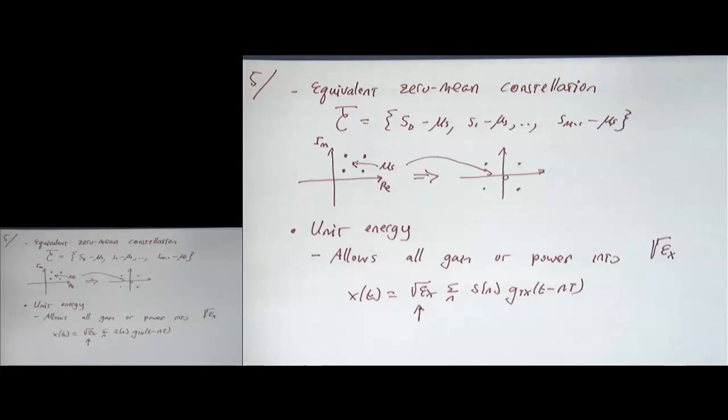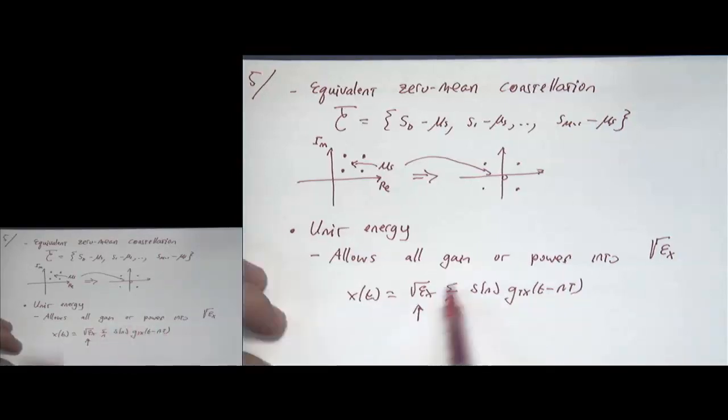So there's no notion of digital gain. You could potentially attenuate the signal a little bit digitally, but because there's quantization and other issues, that's normally not something that we do. So in reality, all the gain is in the analog as well. And so by doing this, this allows us to create kind of a gainless digital signal.